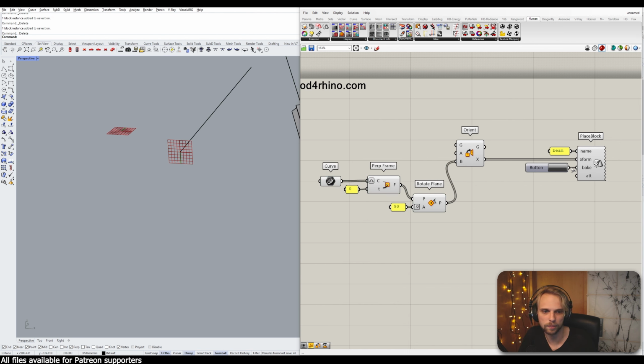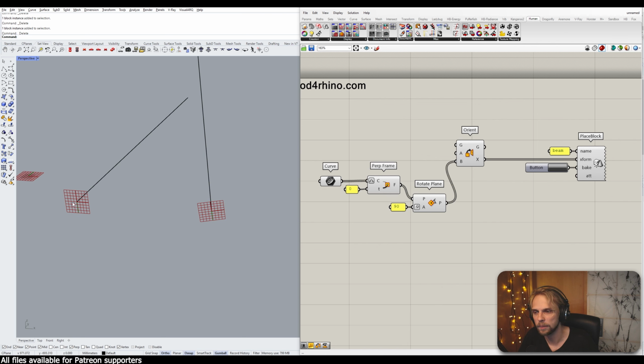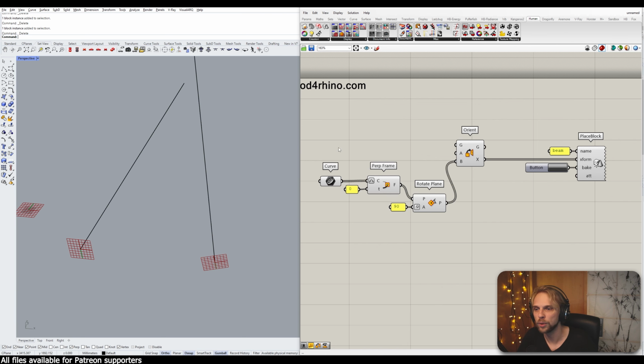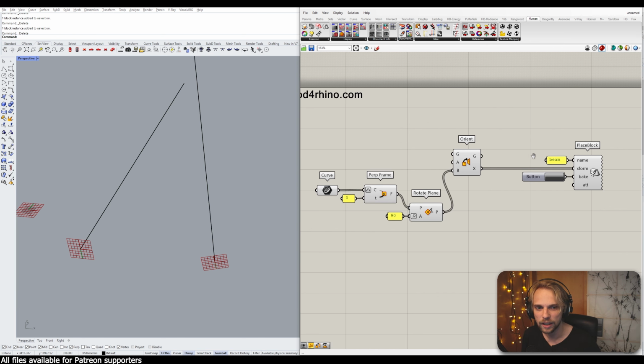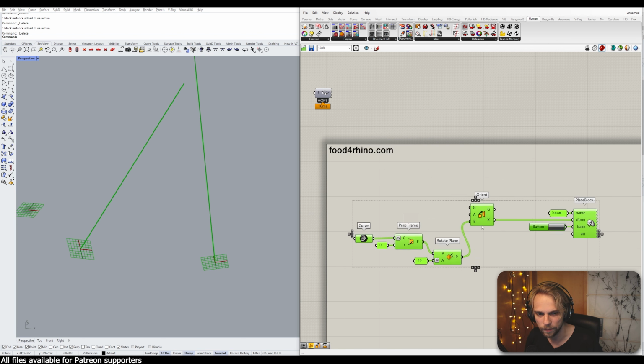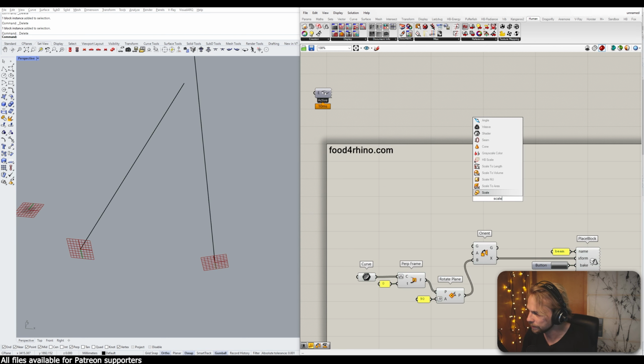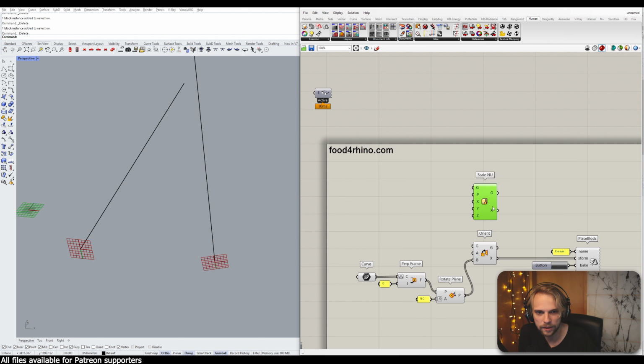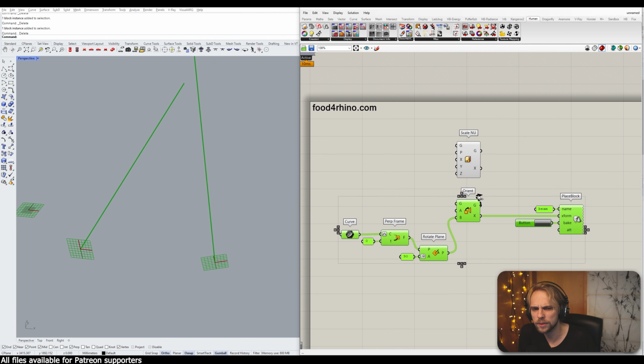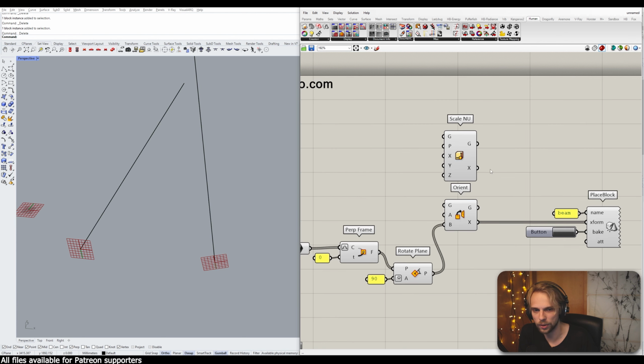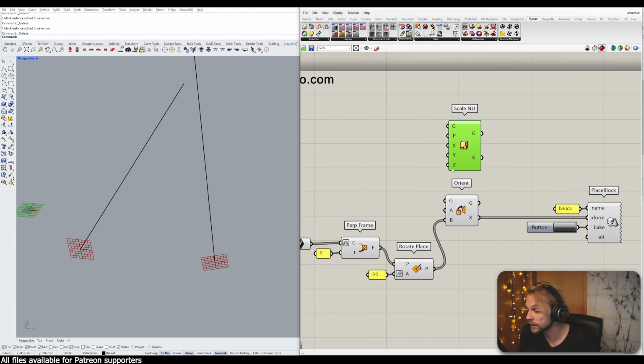We still do have a problem here, and the problem is called my beams are too small, too short. We need to scale them. The problem is if we scale the whole damn beam, well, that ain't gonna do it, right? Because the longer the curve, the bigger the beam, all of the dimensions will scale. So the transform that we're looking for is called Scale NU, scale non-uniform, a stretch basically. Again, we don't really need the geometry for this to work. We only need to scale it along the z-axis.